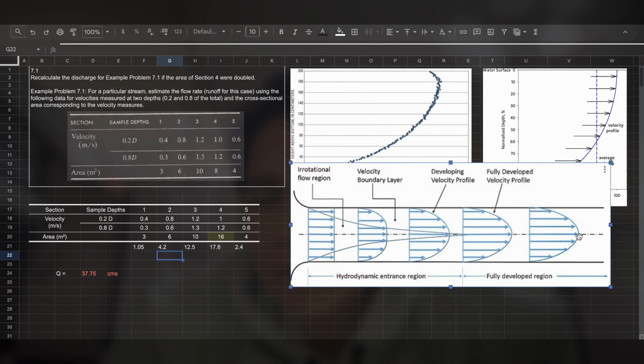Think of the arrows as the magnitude of the velocity. So the arrows at the center are longer than the arrows closer to the banks of the river. So this is pretty much the shape of the velocity of the water in a river. If you see it from the side, it's faster at the top, slower at the bottom. If you see it from above, it's faster at the center, slower on the sides, when you're closer to the banks.